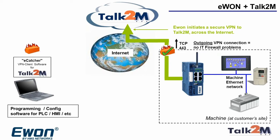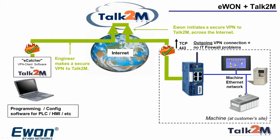On the left-hand side, you have the engineer who has their laptop, and they want to connect to the right-hand side to do some maintenance on the machine, which they're responsible for on the site. So they fire up the eCatcher software, which is a VPN client software specifically designed to connect to Talk2M. Once that VPN is established, they can then see the ends of all these VPN connections within the Talk2M account, which they've signed into, and they can choose to connect their VPN to one of the VPNs from the site.